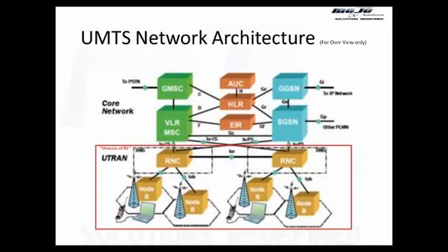The jargon changes. In GSM the base station was called BTS, radio base station, RBS. In UMTS it is called Node B. In LTE it's called eNode B. There used to be an RNC in UMTS and a BSC in GSM, but in LTE there is no more central controller in that sense, though there is still something called MME, which we'll look into.